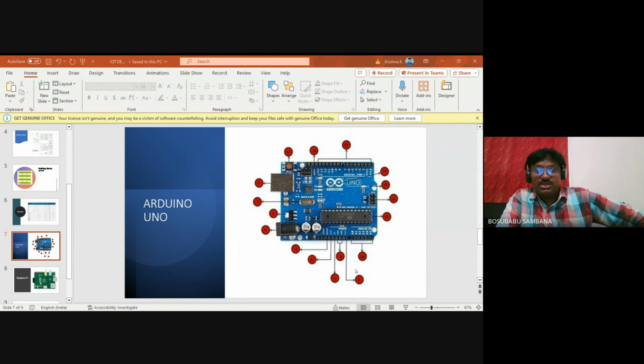Determine which Arduino serial port to use. Use the menu items Tools, Serial Port. This is probably at least COM3 or higher. COM1 and COM2 are usually reserved for hardware serial ports. Disconnecting the Arduino board and then reopening the menu should reveal the answer. The entry for the Arduino board should be gone. To use that serial port again, reconnect the board.